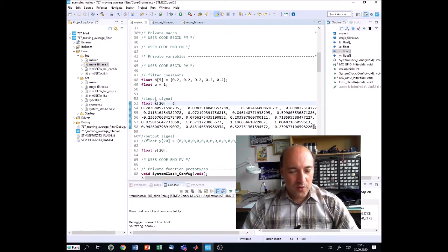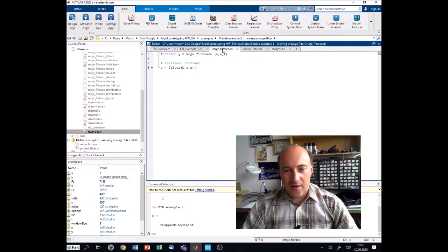So what my code will do is that I will take this sample one by one in a loop, and I will run the filter on the sample. I will calculate the output signal, which will be Y here, and then I will do this step again for another sample. So it's always done sample by sample. In fact, in MATLAB, we have done a very similar thing.